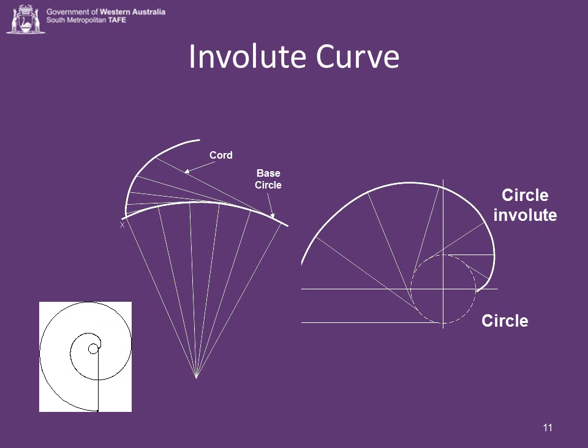We use the word involute because the contour of gear teeth curves inward and is used in gear tooth profiles. The involute curve is a curve that is traced by a point on the end of a taut line unwinding from a circle. The larger the circle, the straighter the curvature.